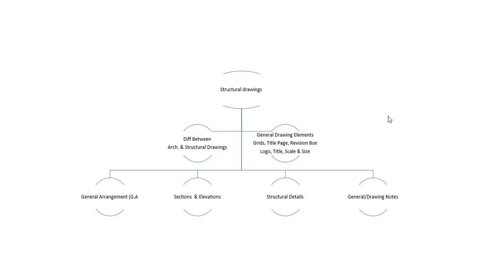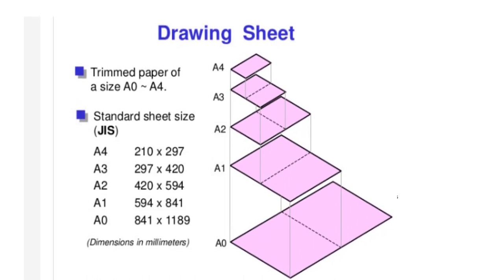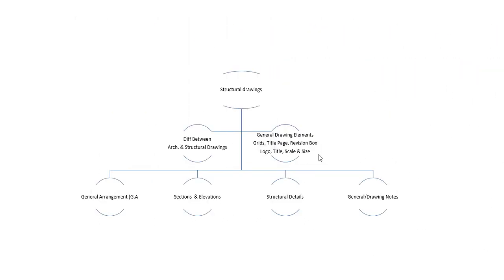Also drawing size and scale details. Two pieces of information: the intended drawing sheet size and the scale of the drawing sheet when printed at that sheet size. So that is one of the most important points there. And we have a few general notes, which include the common instructions that need to be followed on site, let's say concrete cover, grades, specifications related to reinforcement detailing, foundation depth, lap lengths, etc. We will go further into detail with the example of a particular drawing.